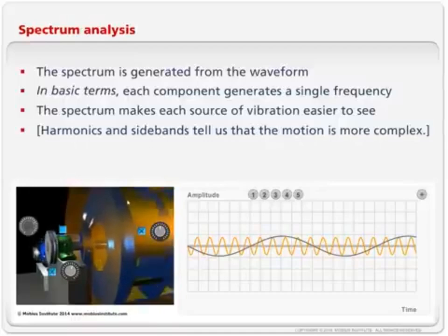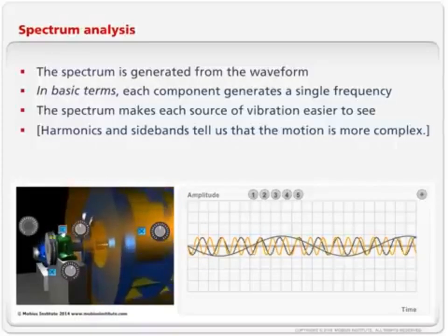That vibration transmits through to the shaft up here to our measurement location. Now, in addition to the fan vibration and the shaft vibration, so the grey shaft creates this grey vibration, the orange fan makes the orange vibration. Well, the green bearing, just to really simplify things, it also creates vibration. Let's just turn off the other one so it's a bit easier to see. And this is the green vibration from the bearing.